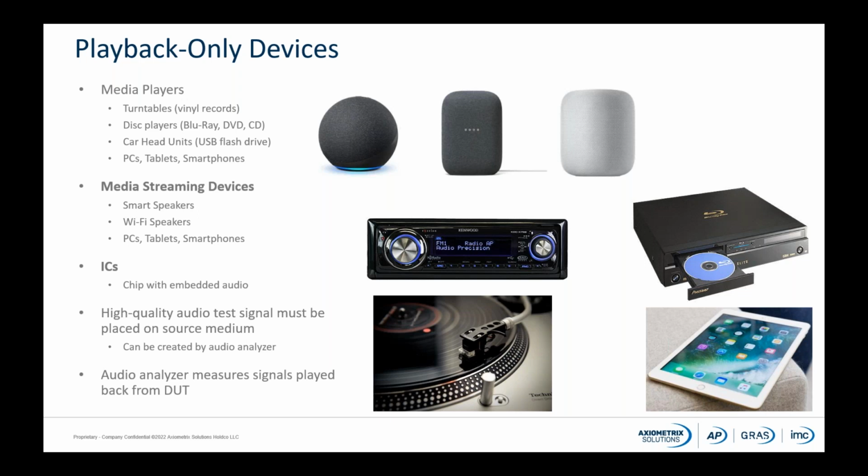DUTs which require open loop testing fall into three main categories: playback only devices, record reproduction devices, and broadcast or transmit devices. To test playback only devices, the stimulus signal must be placed onto and then played from the device, or streamed into the device and played from its output into the audio analyzer.